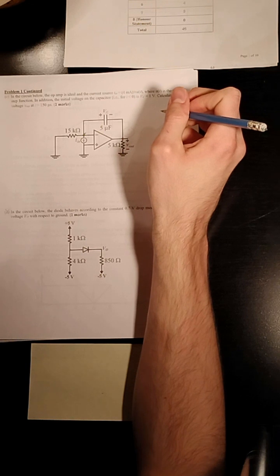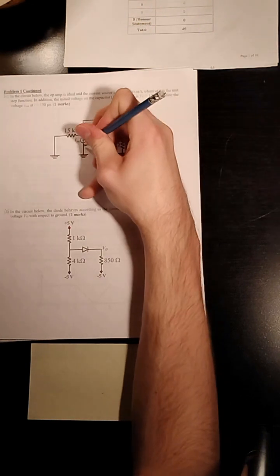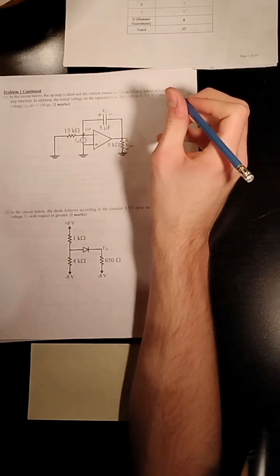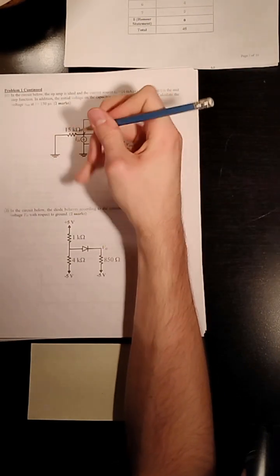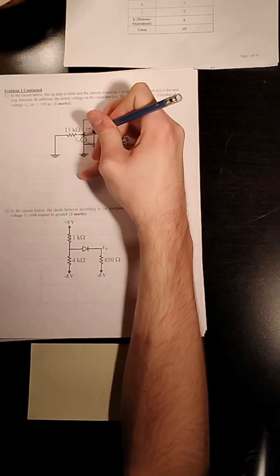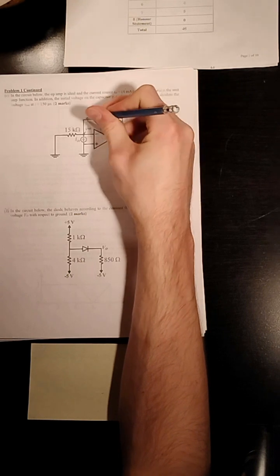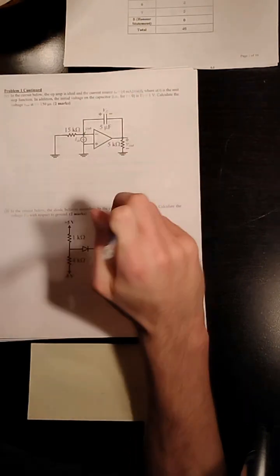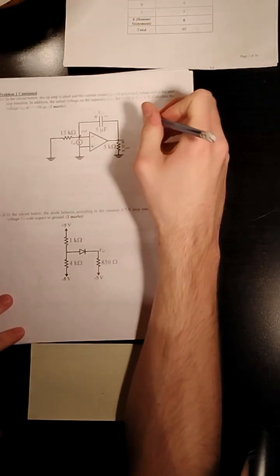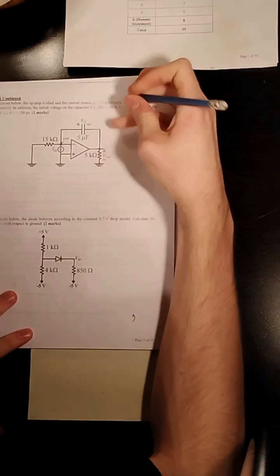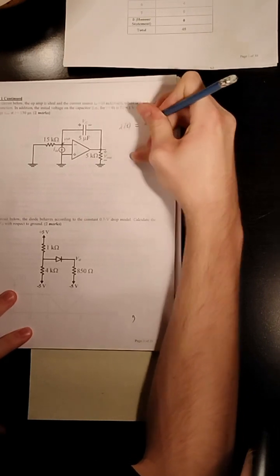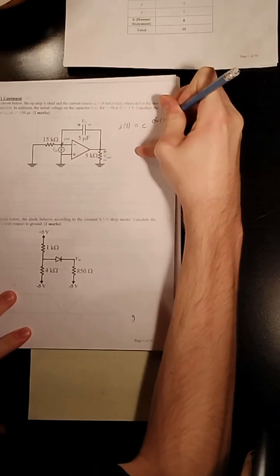Right? Yes, because this voltage is grounded. So this has to be 0. So you can't get any current through here. So all of the current going through this current source has to have come from the capacitor. Now, you can turn back to your formula for voltage through the capacitor, which is C dV of T by dt.